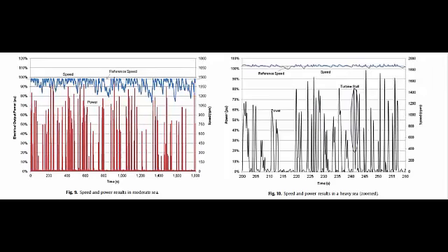From tests conducted over a range of pneumatic input power levels, it was clear that at high mean pneumatic input power levels and low rotational speeds, the aerodynamic stall characteristic of the turbine significantly reduced the power output. However, at lower mean pneumatic power inputs and lower turbine speeds, the power output was enhanced.